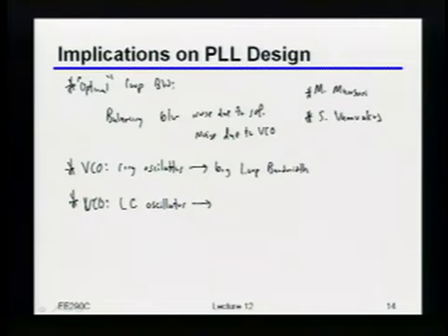So in that case, what do you want to do to the loop bandwidth? Small. Yeah, you basically want as small a loop bandwidth as you reasonably can get. Now obviously you're never exactly in one of those two situations. There's always some balance point in the middle.